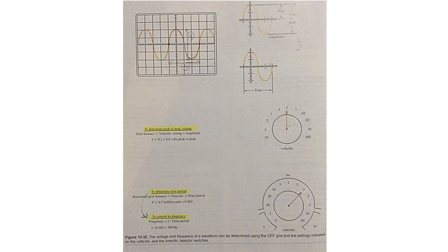The small lines running up and down the center of the display are used to assist in making accurate measurements. The small lines divide each grid square into 5 equal parts. Look again at figure 10-32. The sine wave pattern covers a distance of 4 grid spaces from top to bottom. If the volts/div selector switch is set on 0.2, then the voltage amplitude of the waveform is equal to 0.8 volts peak to peak.